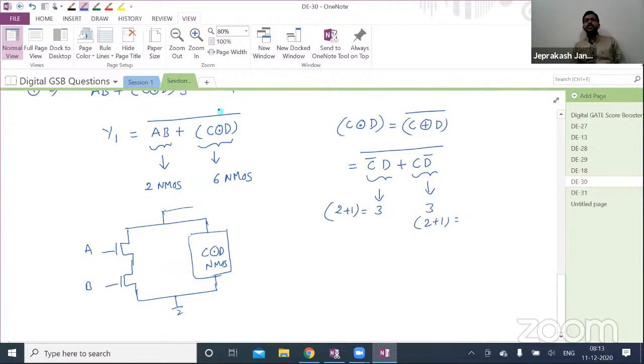By default, you will get the complement version. And similarly, you will be having PMOS logic on top. Here, if it is series connection, there they are parallel connection. If it is parallel, they are series. Up to this step. All of you please respond.